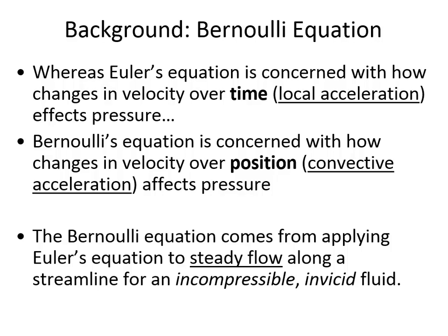Later on in the semester, we'll get to an equation that can handle fluid viscosity. But Bernoulli's equation only applies perfectly for these ideal fluid conditions. Now, we'll still apply it even when we have a fluid that is compressible and viscous, but when we are in the lab and our measurements don't match up exactly to what we'd expect, you should write a note to yourself for the lab: you're not going to have exactly what you'd expect.